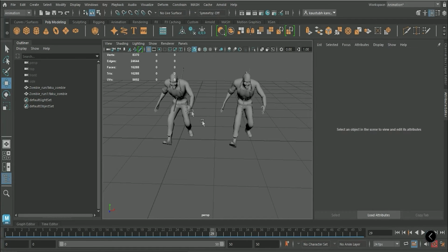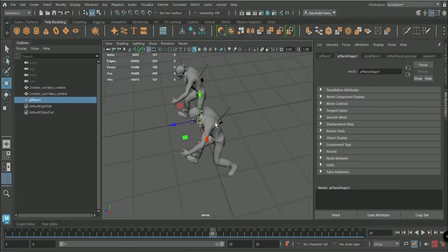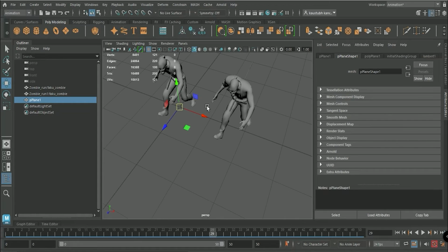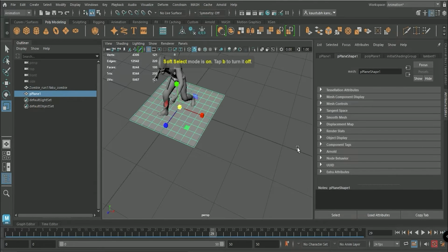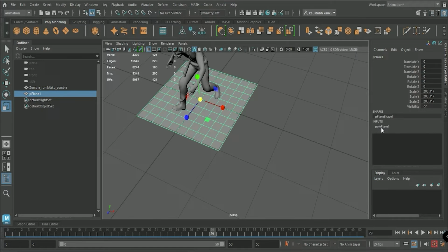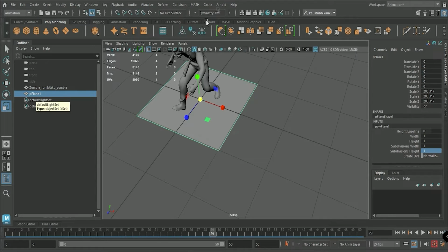We will set up a plane so that we can create our mesh file. What is that? I will tell you in a bit. Now I will create this plane. I will do this with only one character for this video. I want only one face, so this many faces are not required. I will go to polyPlane1 and keep width 1 and height 1. Now by selecting this plane, I will go to Mesh and Create Mesh Network, Mesh Options.